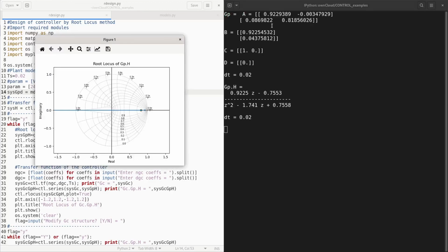You will see that the discretized version of the separately excited DC motor is GPH, converted into a single input single output system. Therefore it can be expressed as a transfer function, GPH, like this. You have two poles, one pole here and one pole here. There is no pole at z equal to 1, and therefore you will see a steady state error.